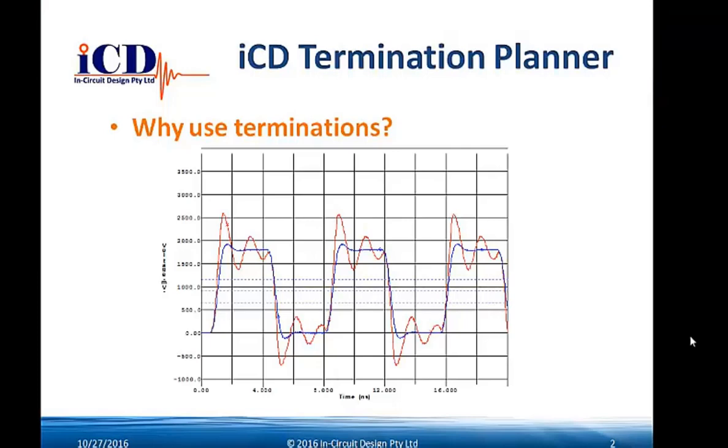High-speed design is all about impedance. For perfect transfer of energy and to benefit from the highest possible bandwidth, the impedance of the driver must equal the impedance of the transmission line. Unfortunately, driver impedances are all over the place. They can range from like 12 ohms to 80 ohms. So the idea is that we need to match that driver to the transmission line so that we perfectly transfer